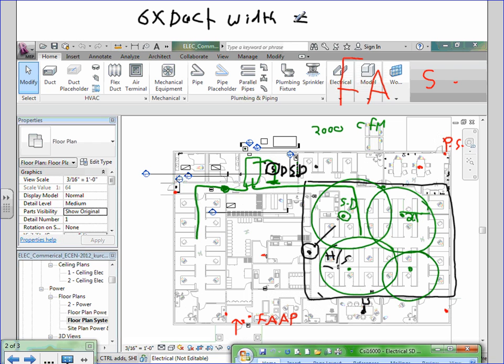So no, it's on any duct. If this was a ducted return, so there were return ducts that went throughout this entire space, then you would want to get 6 duct widths away from that air handling unit, because there's more space to deal with. Right now, all you have is this little chunk of duct that's going into the ceiling space in the corridor. I'm not even sure if you have 6 feet.